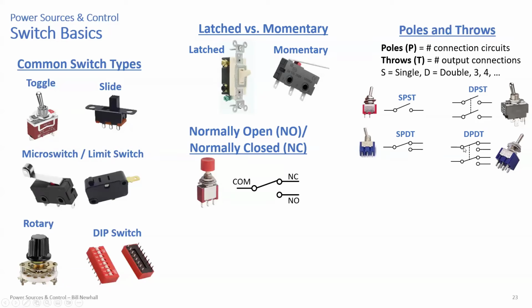All right. Here's another switch. Here's a four-way switch. These are typically in homes. A four-way switch works like this. Here's the schematic symbol for it. A four-way switch is either in this configuration or in this configuration, where there's no connection where the middle of the X is. So a four-way switch either goes straight through for those top and bottom pairs of terminals, or it crisscrosses like this. Okay, so that's a four-way switch.